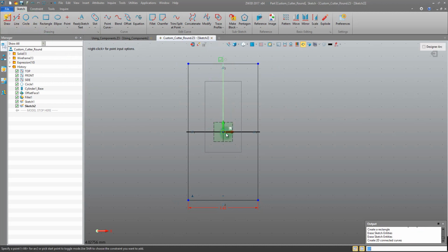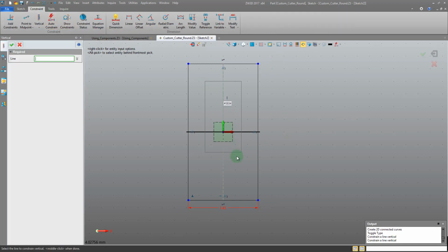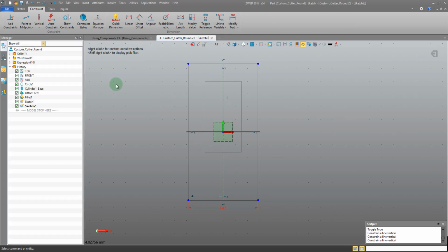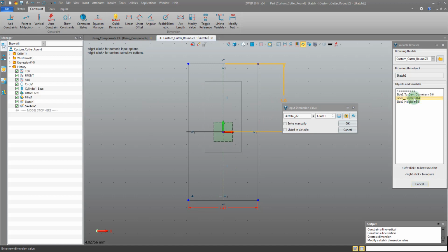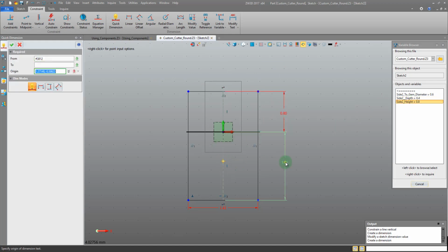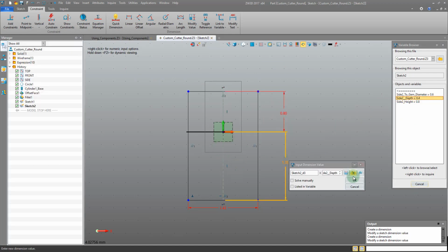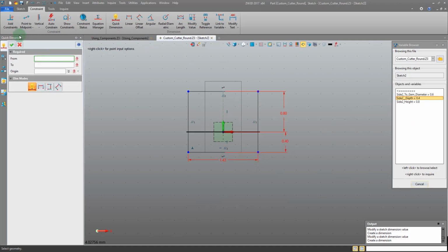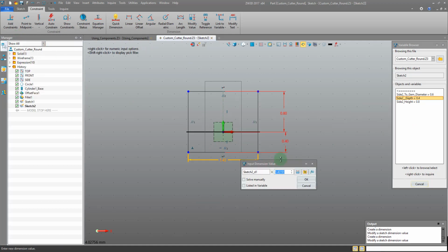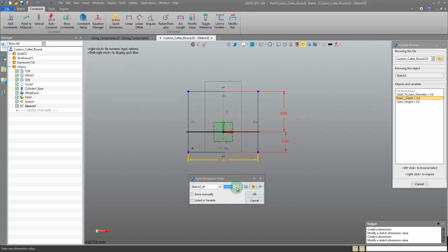or we could draw 2 at the same time. Just straight down, middle click, control picking, toggling them to construction. We need to constrain them to be vertical. And then we right click and dimension them. And this is the height. Again, I'm really zooming through this because it's not really the focus of this tutorial. We can create a component in any fashion we want. And then the important bit will be how we can apply it to our main build.